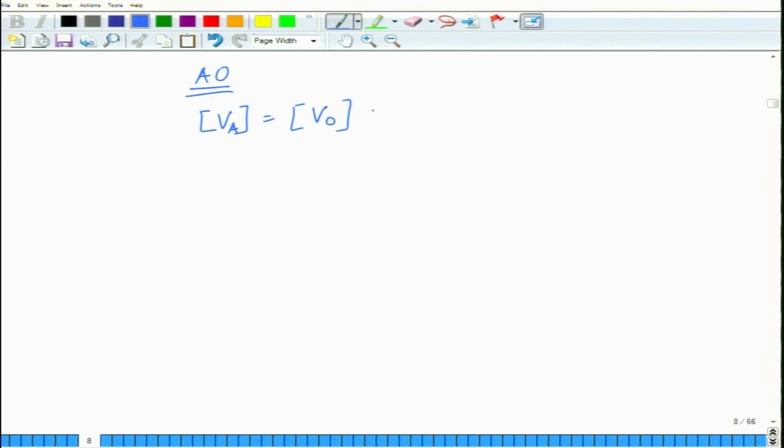So this would be 2 minus, this would be 2 plus, and this is basically the total number of sites N exponential of minus delta Hf, which is the enthalpy of formation of vacancy, divided by 2kT. So here you have this factor of 2 that comes in the denominator for ionic solids, but the relations are similar, all right.